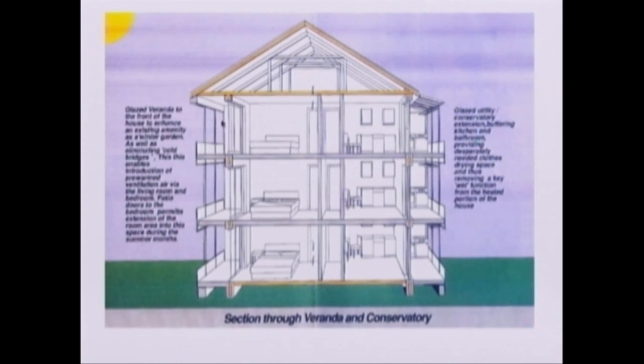Now of course the possibility exists, we've got glazed spaces in each side of the building, orientations change. We could actually make use, depending on orientation, of more than one side. But if we just stick to the idea of using one roof surface, that would give us 45 square metres of PV, in other words 15 square metres for each of the apartments on each side of the stairway.